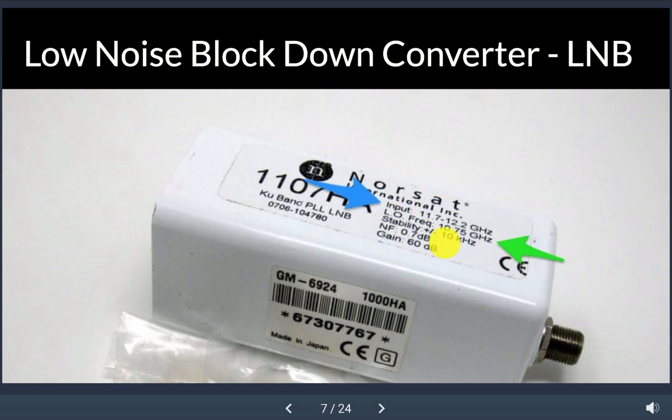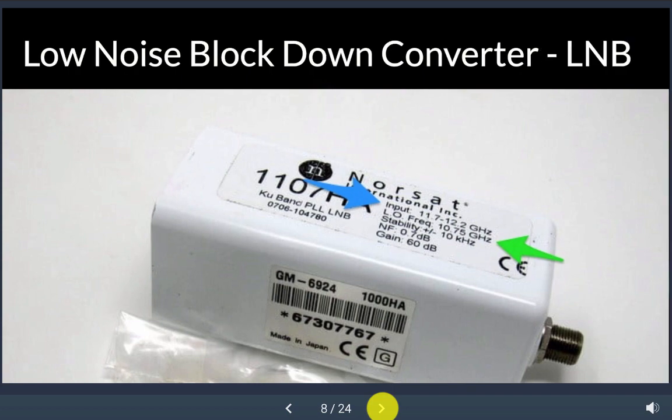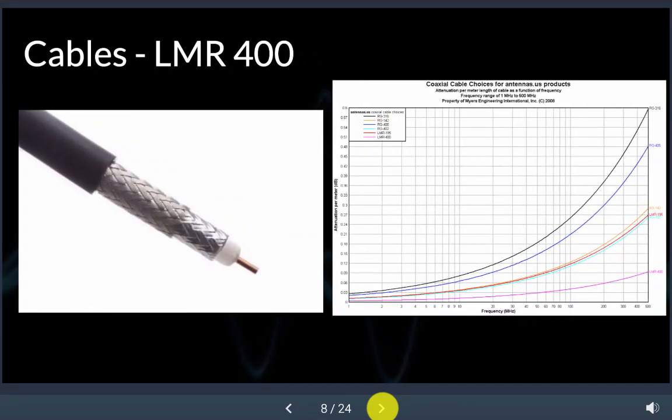This is just kind of a blown up picture of an LNB. You can see here that this one will take an input of 11.7 to 12.2 gigahertz. Our target frequency is at 11.8, so it's within that range, so it will work for our purposes. The local oscillator frequency on this one is 10.75 gigahertz. That's pretty much standard for this particular Ku range, but that's not always the case. They could be different. Different local oscillators are going to give you different results coming out the other side.